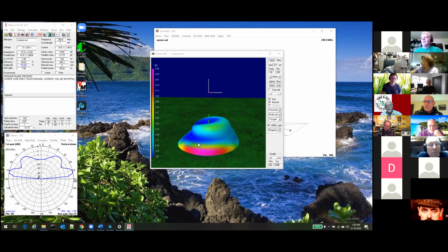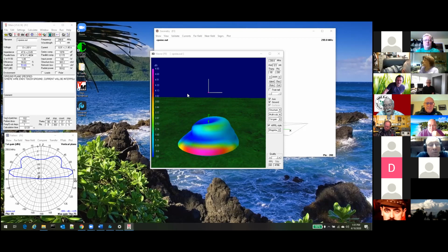What I have for my satellite antennas are 2 egg beaters, and they have the 4 aluminum rods for each one. And it works pretty well. It makes it hard to work a repeater because I have nulls in the lower part of it, but it's fine for working satellites where I'm using high elevation work.